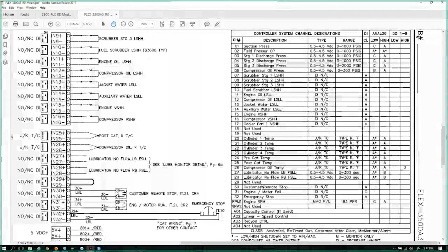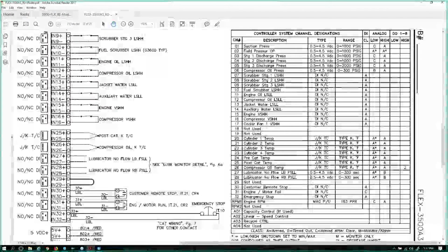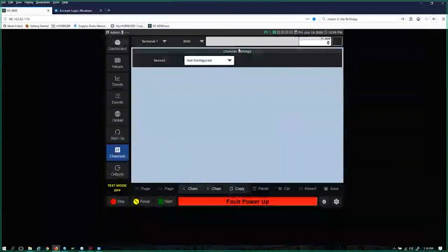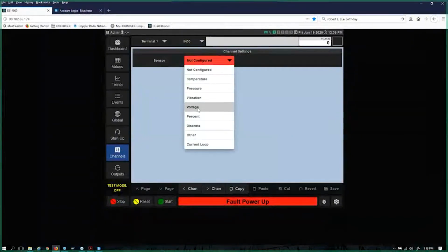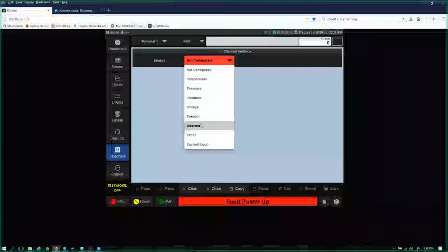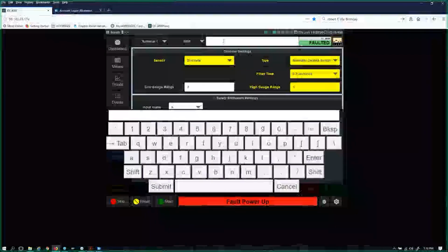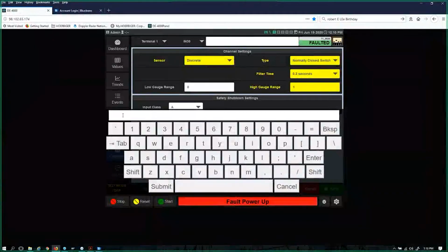My demo is I have a simulator for this wired into channel 30. So I'm going to fudge the demonstration just a little bit and jump straight to channel 30. We're going to call this a discrete. I'm going to call it a normally closed. I'll go on and name it. We'll name it Lube No Flow.